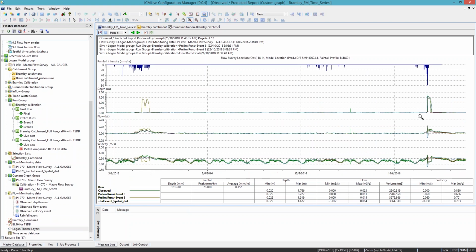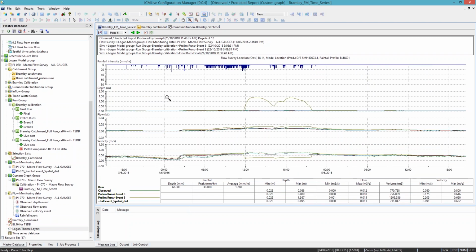So once I started tweaking that parameter, what I was able to do was, because it had been dry beforehand, the soil store has to fill up a little bit before it starts contributing to the sewer. So we found that focusing on event 6, the gym didn't really contribute much at all to inflow to the sewer during that event, because it was probably a longer duration, lower intensity event. So I set the percolation threshold accordingly, and it did fill up the bucket, but the bucket only started contributing a bit of slow infiltration towards the end of the event.